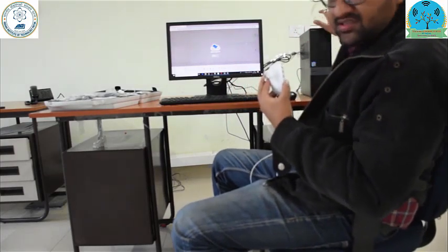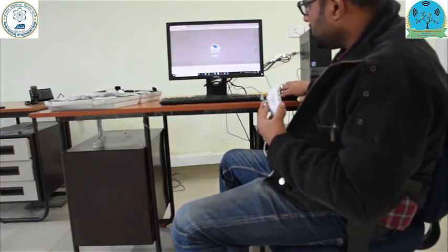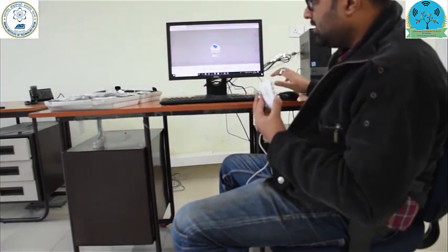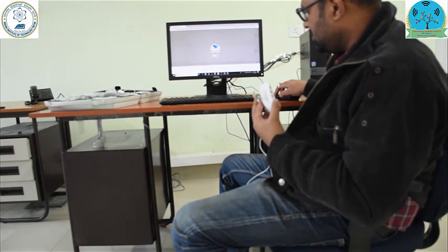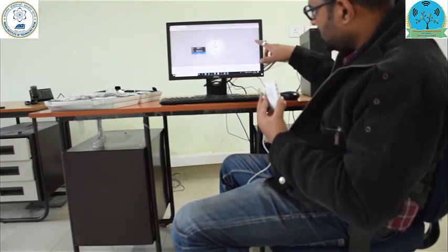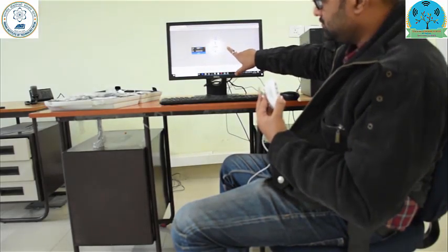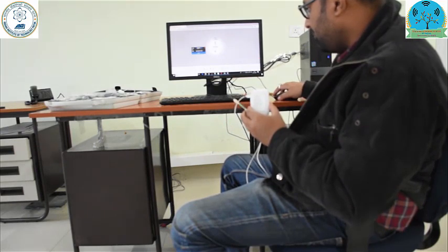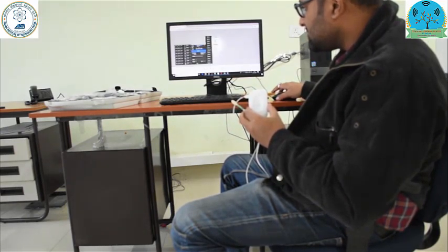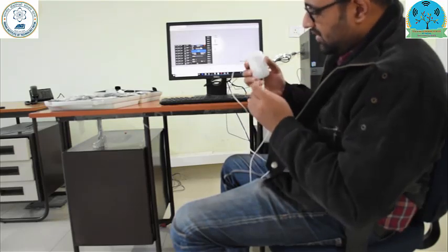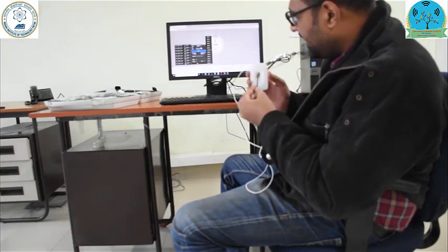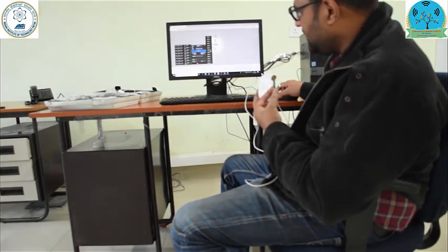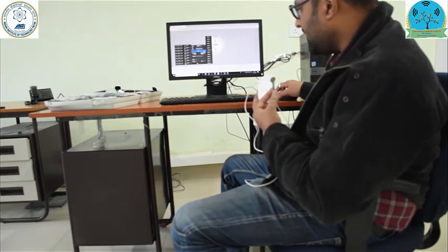Now, in the Bluetooth-enabled system, when I open the OpenSignal platform, the UI is like this. The first step is to connect it to the system. For that, we have to find the devices. When we click on find and configure devices, it shows one device found, which is the OpenSignal Bluetooth device, and we can verify this with the MAC address given here. We enable this device, and as I told you, it is configured on channel 1, hence we will enable custom channel 1. We'll use a sampling rate of 700 Hz, which we'll select from here, and we'll enable the device.